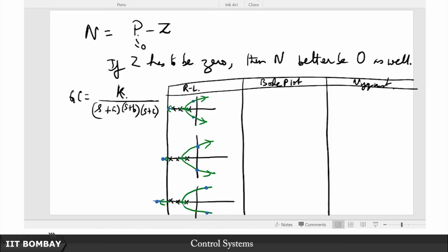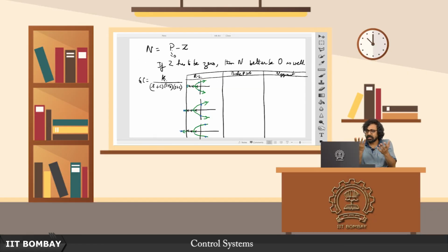Not always, but in this case, as you can see, there are three unsatisfied poles, so of course there will be three asymptotes, and two of them will migrate to the right half plane, so that's inevitable. So we have this in one case for lower values of gain k, so this is for low k, this is for critical k, and this is for high k.